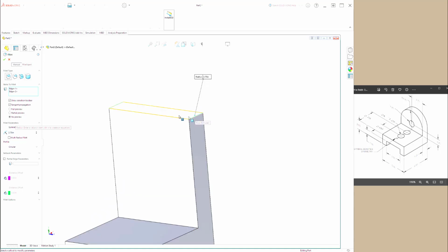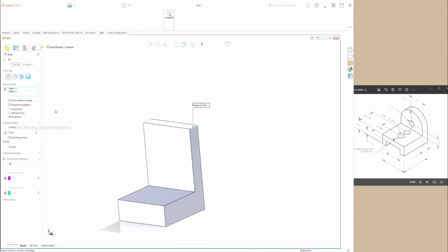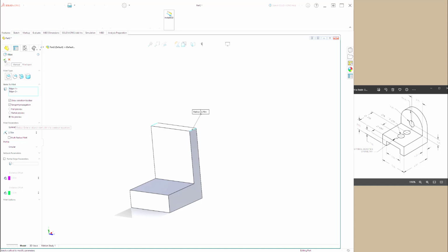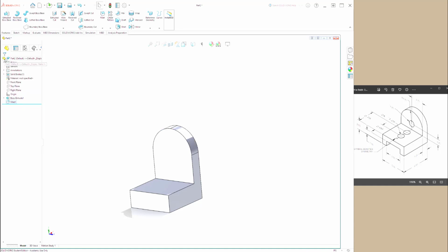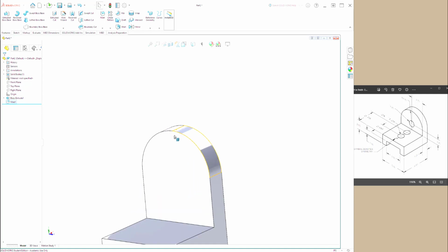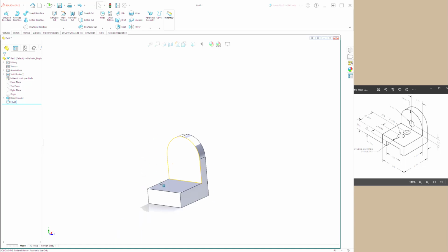So if you mispick something, all you do is go into the window, highlight it, and hit the delete button to have it go away. And we choose the OK button, and it should fillet the top perfectly, which it does. So that was pretty cool. So that's the fillet tool, and we use the radius. Now again, it knew exactly that the 2.75 would create a perfect radius across the top.